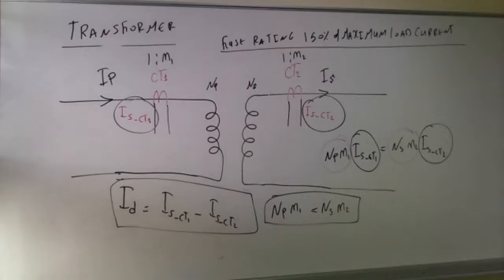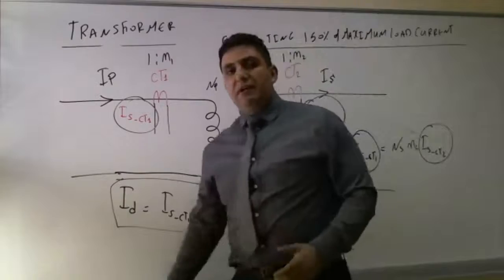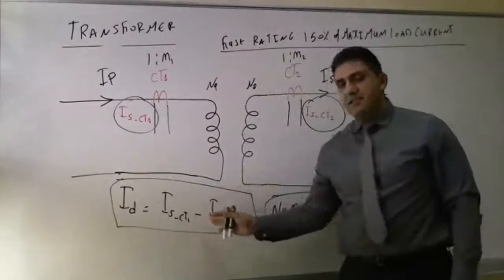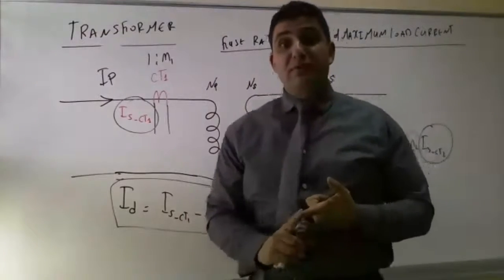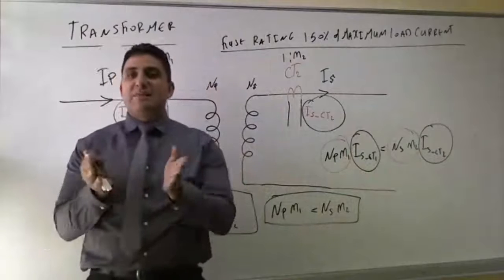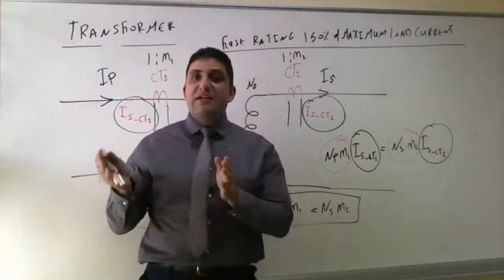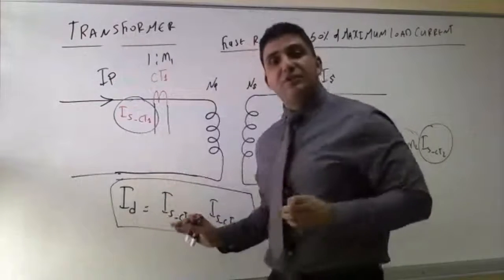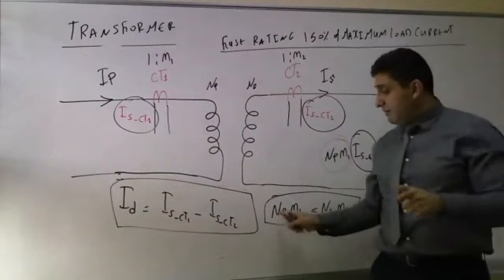Now, what's an error? Why do we have an error? Number one, the error exists because of CT ratio mismatch. Number two, remember the CT chapter? Inside the CT chapter, we clearly explained the CT error, the I magnetization divided by I2. Remember this from the previous chapter? This is the second error. So the first error is the mismatching error.